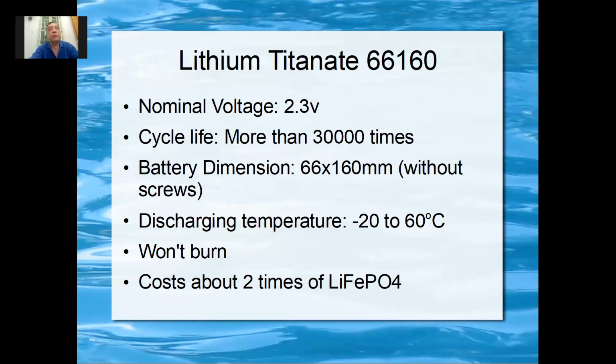They assume that you don't use until flat. If you use your phone until it's flat, and then you charge until 100%, then discharge fully, and then charge again, then you won't get 1,000 cycles. Or even if they put 5,000 cycles, you won't get it. So you get much less. So the number of cycles doesn't mean that you can discharge fully. It's only 20%. But for lithium titanate, it's not an issue.